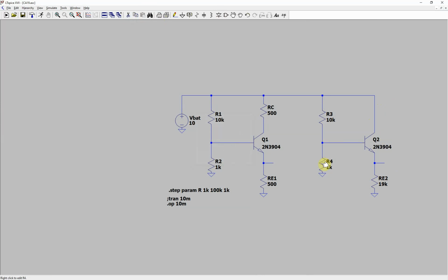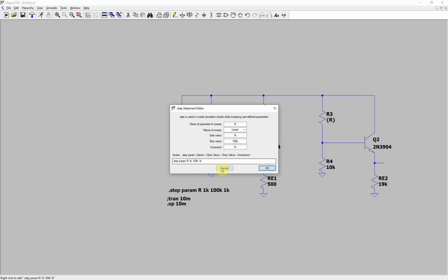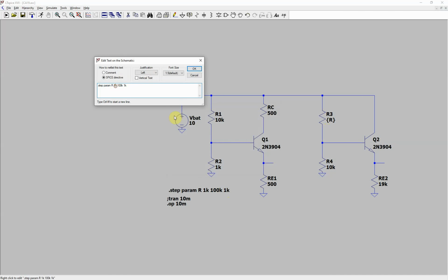We're going to want these bigger. We want these to be a lot bigger than the 500 ohms because we don't want loading between these two. So this is 500 ohms, so let's do 10 kilo ohms. And in this case, we want this to be at least 10 kilo ohms.